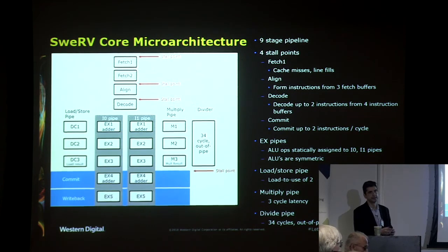I think one way to look at it is processors, depending on how they're being used. If you're going into, say, a PC, then you want the fastest single stream performance. But if this is a small core used as an embedded controller, programmed by firmware to control hardware, the interrupt latency is a very significant attribute of the processor.